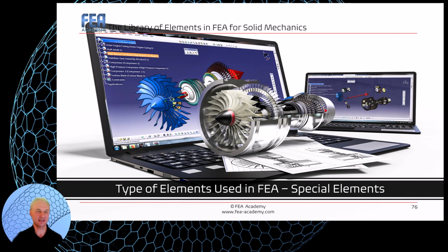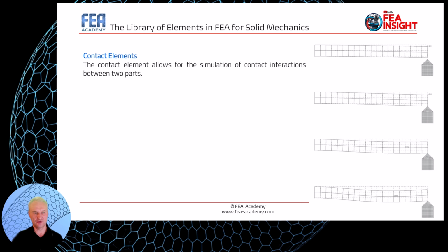So now let's discuss a little bit about special elements. The first type of special elements is contact elements. The contact element allows you to simulate contact interactions between two parts.